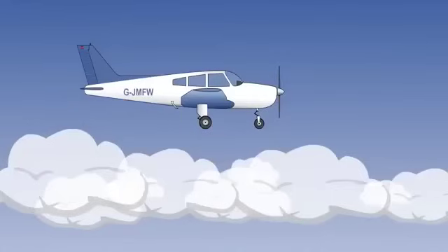There is a rapid formula for use in the air. It is simply that the ram rise equals your true airspeed in knots divided by 100, all squared. So that if your TAS is 200 knots, the ram rise is 4 degrees. And if your TAS is 300, the ram rise is 9 degrees. And so on.